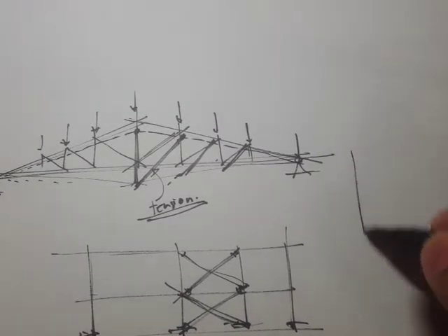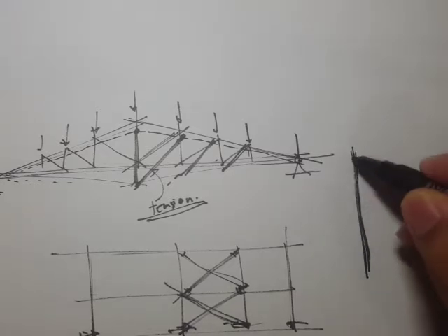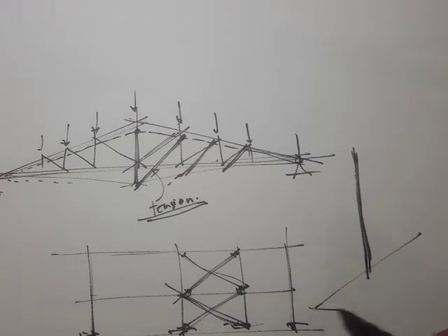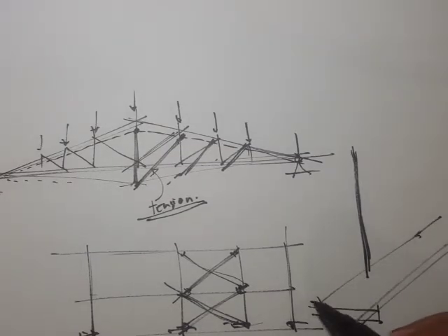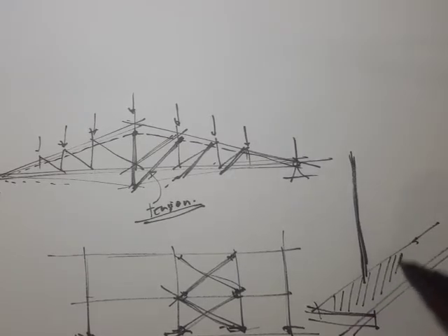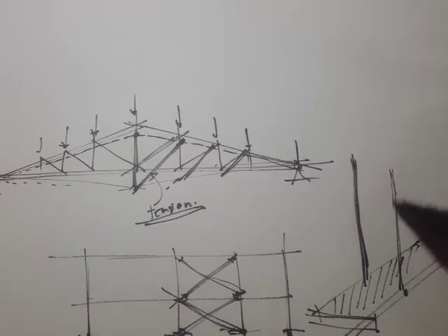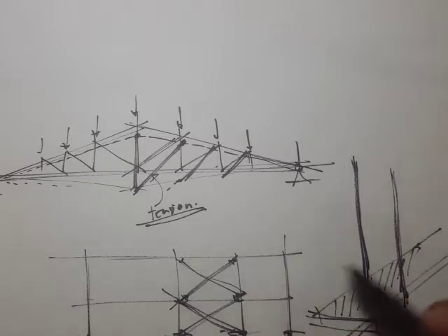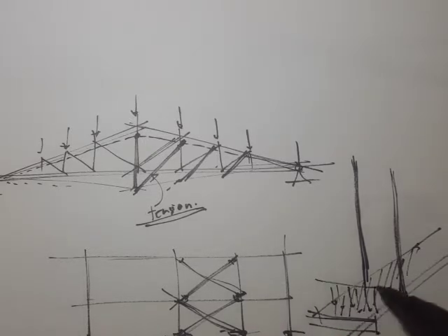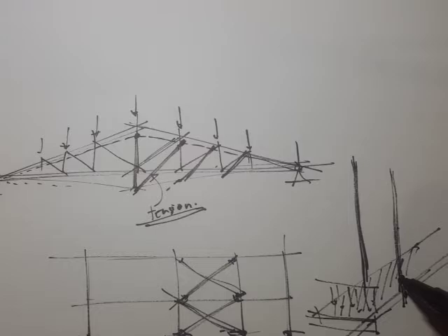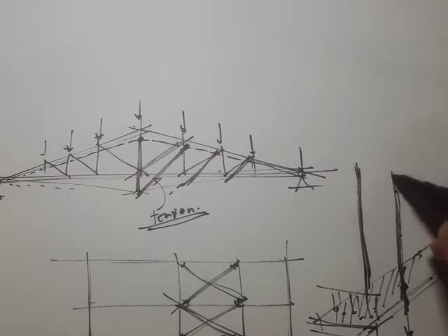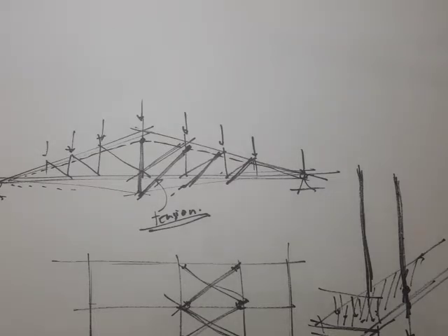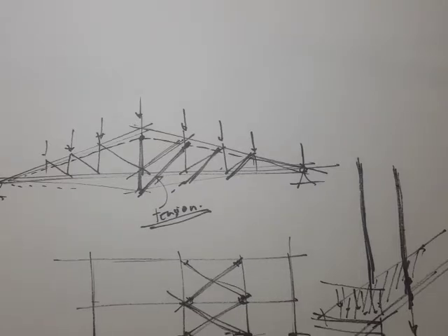And also, tension members are common in suspended cables, like for example a platform. Let's say this is a platform, and this platform is being supported by cables. So if you have a load on this platform, then you're inducing a tension force on these suspended cables. Those are the typical applications or situations where you can find these tensile members.